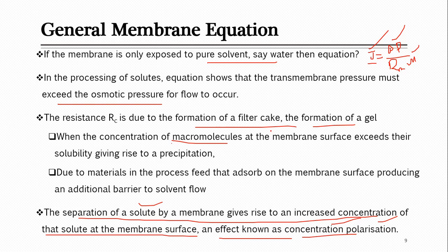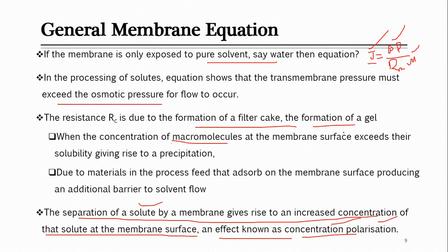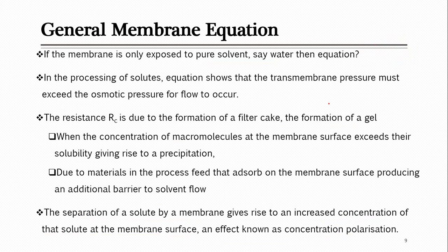So these are the general parameters which you should keep in mind when you are designing a membrane system: pressure difference, selection of membrane material, resistance due to cake formation, and viscosity are important parameters which can give you a bit clear idea about some system. Although again, if you design some system, because you are not accommodating all the parameters of interactions, maybe you were expecting more flux but you are getting less flux, so there can be some other problem inside that, but this is somehow close to the real systems.